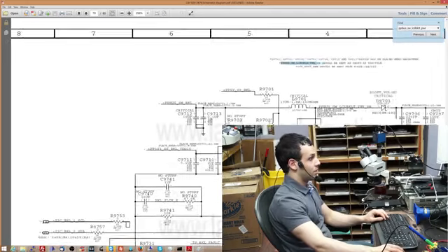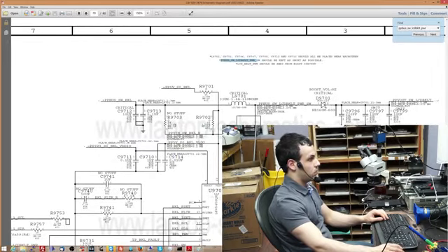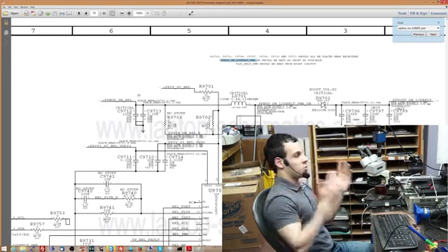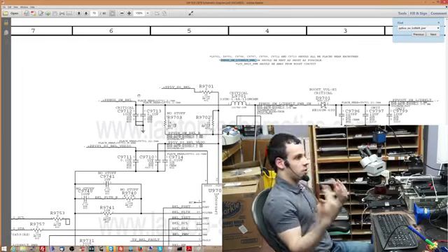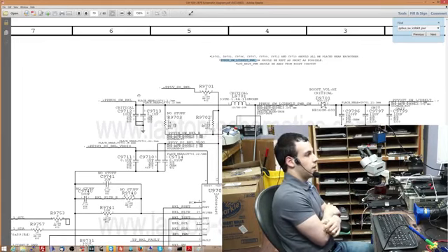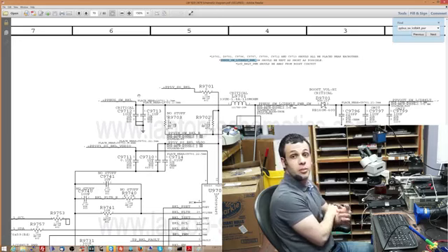So what's the rest of this circuit? If you watch the rest of my videos, you should know. This says SW for switch. The switch is sitting right in front of an inductor. Right in front of the inductor are a bunch of large smoothing capacitors before an output. That output is 50 volts, whereas the input of this circuit, as you saw when I searched for ppbus SW BKL, is 12 volts. So this is a circuit that takes 12 volts and turns it into 50 volts via an inductor and a switch and smoothing capacitors on output.